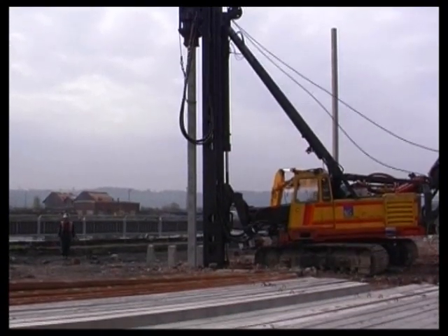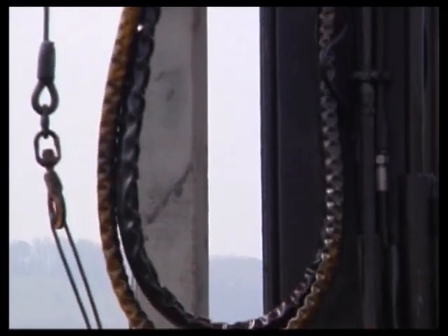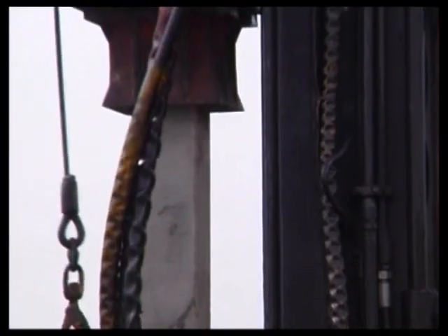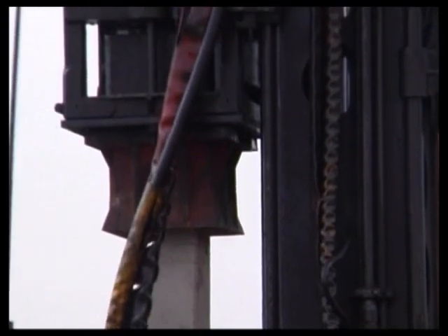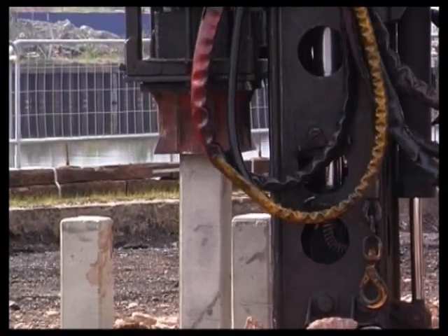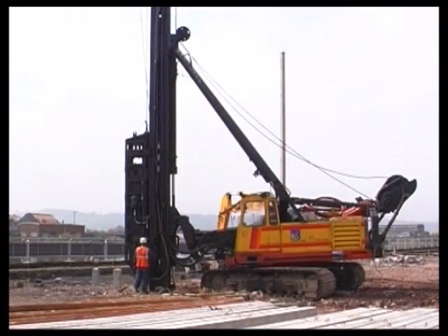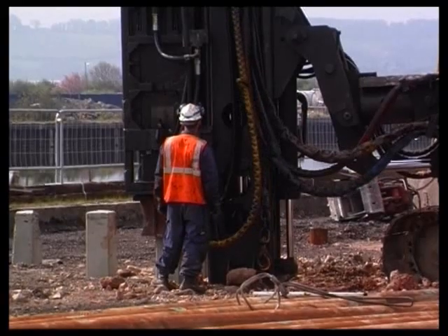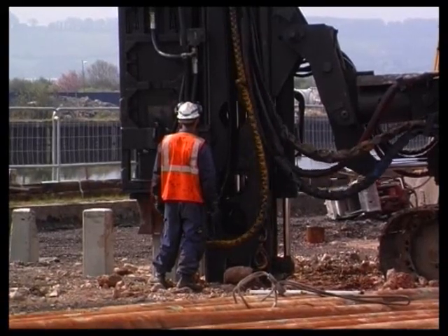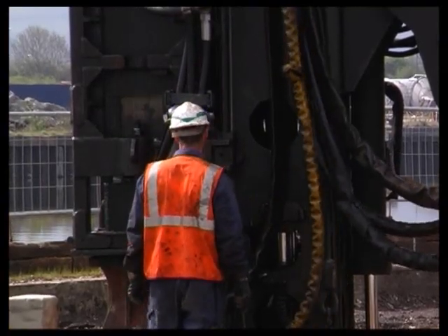Site investigation suggested that pile depths might be between 10 and 20 metres. The piles are driven into the ground by a crane-mounted drop hammer. As the pile reaches a firm bearing, it becomes harder to drive. Design calculations showed that adequate support would be achieved when 10 hammer blows couldn't drive the pile more than 10 millimetres into the ground. This is known as the set.